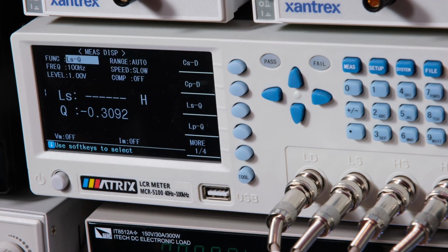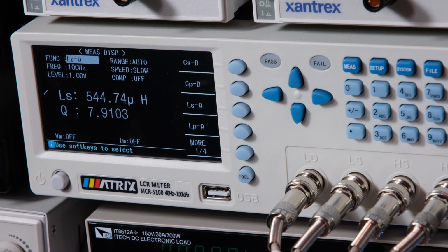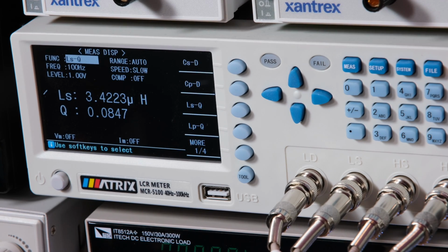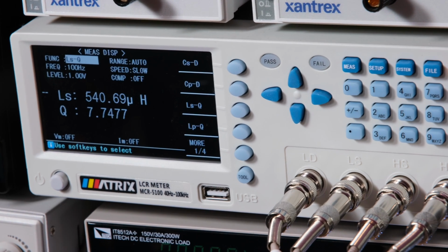Now if I move that and put them in series like I did before where it's common mode, I get 2.4 millihenries. Now if I just look at one side, so one side is about 500 microhenries, right? Now I'm going to short out the other side, and we're back to about 3. Okay, I'll short out the other side, we're about 3 microhenries. So if I wrapped it tighter, we'd get a little bit better coupling and probably a better example.